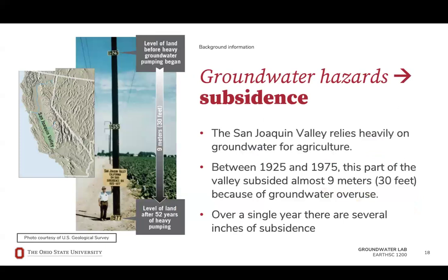An example of subsidence can be seen in the San Joaquin Valley. The semi-arid Sacramento-San Joaquin Valley of Central California is known for its agricultural products, from citrus fruits and wines to grains, cotton, and rice. The area produces a quarter of the food in the United States. Heavy pumping of groundwater for crop irrigation has lowered the water table, causing more than 9 meters of subsidence in some areas of the valley. That subsidence threatens agricultural production, large water supply lines to major metropolitan areas, and important ecosystems.